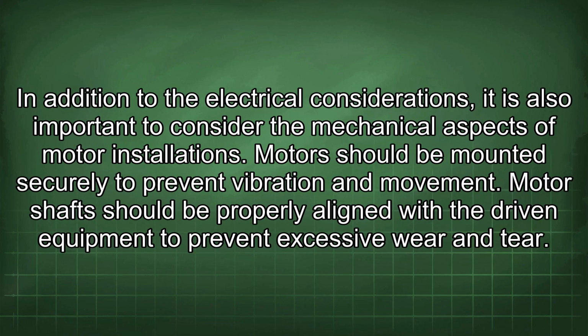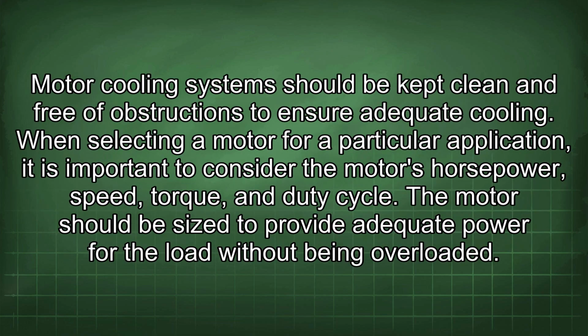In addition to the electrical considerations, it is also important to consider the mechanical aspects of motor installations. Motors should be mounted securely to prevent vibration and movement. Motor shafts should be properly aligned with the driven equipment to prevent excessive wear and tear. Motor cooling systems should be kept clean and free of obstructions to ensure adequate cooling.